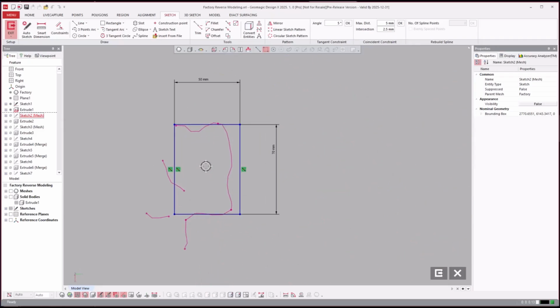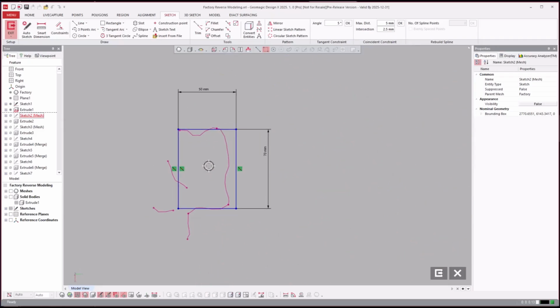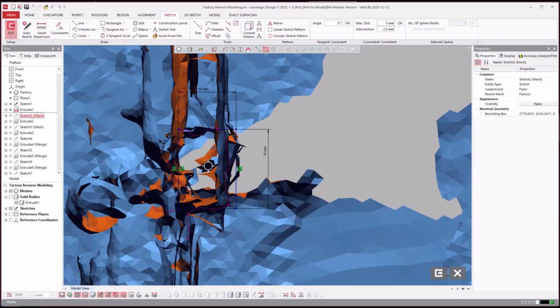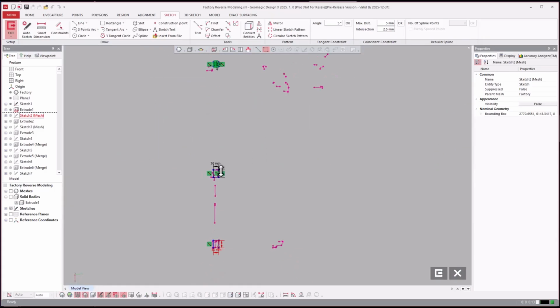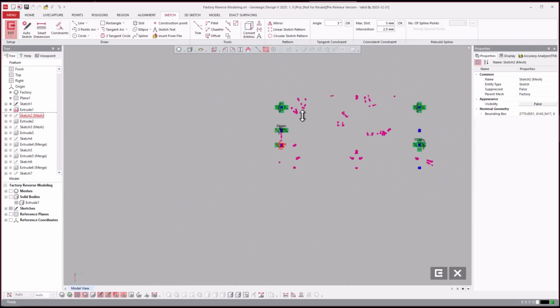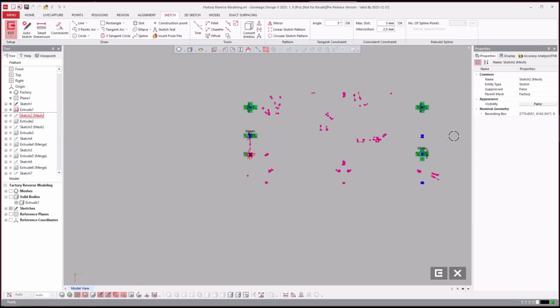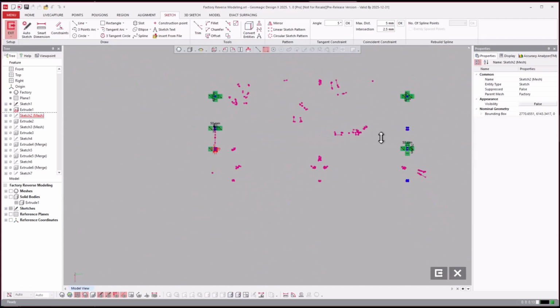And you'll see with long range data, this is a shift in thinking here. If I turn on the polygon mesh, look at there's lots going on. And the idea is I know that this is 50 by 70 millimeter box tubing. I'm going to model it in this position in order to extract and simplify it and use it for design purposes here.